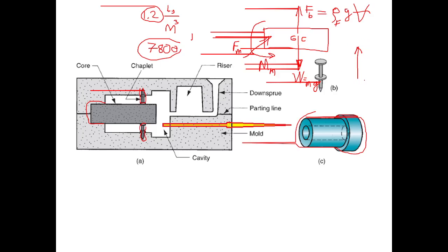Well, shall we balance the lift only having such a reaction force system exerted by the mold? Well, mold is not a strong material. It is made of sand particles. If the lift is too much, then the reaction forces applied by the sand mold to this end of the core won't be sufficient, and the mold will be damaged. Well, the buoyancy lift force will lift the core while it is lifting in the up direction.